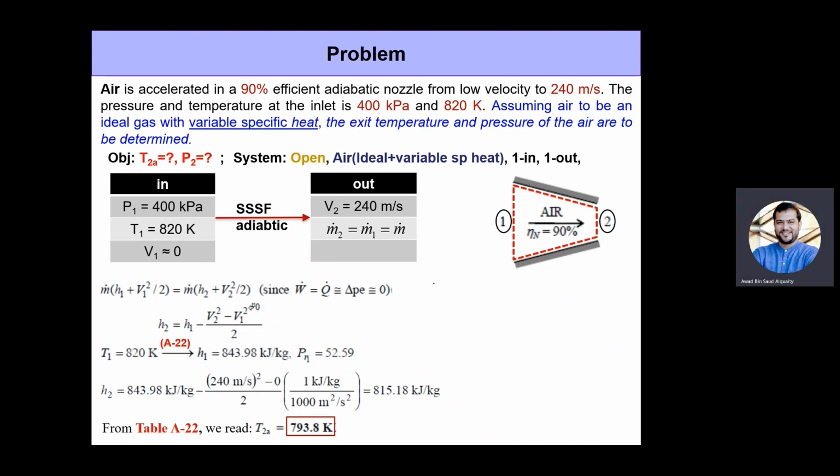All right, so now let's look at the second part of the problem, P2. Right, we need to find the pressure at the exit. Now we have discussed it several times that for all these isentropic processes, the pressures P1 and P2 are fixed. So P2 is exactly equal to P2S, right? And we have a formula relating the ratios of pressures in an isentropic process to the ratio of relative pressures, right? So we can say that P2 by P1 will be equal to PR2 by PR1.